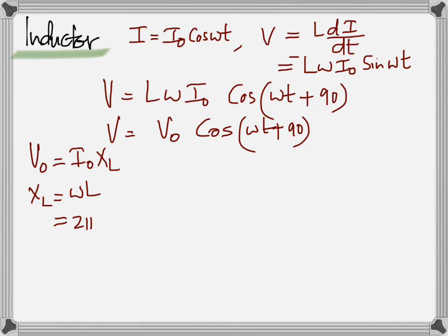But the moment you start increasing the frequency, let's say you start giving it AC now, and the frequency of AC is like 10 hertz, now you know there is an opposition, isn't it? There is a reaction. What happens if you increase the frequency? It gets bigger and bigger and bigger. So now you see a strange behavior of an inductor.